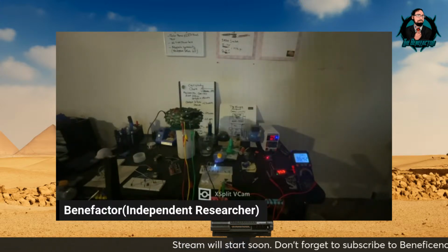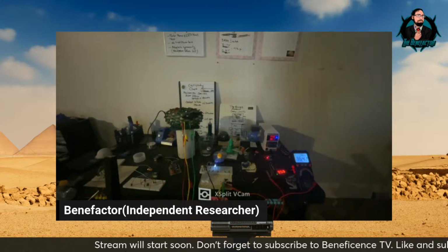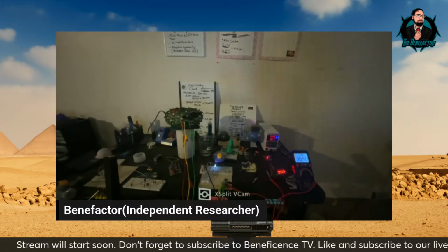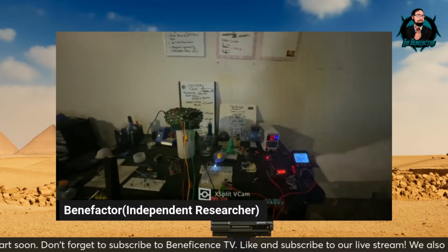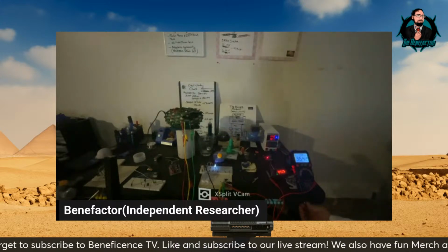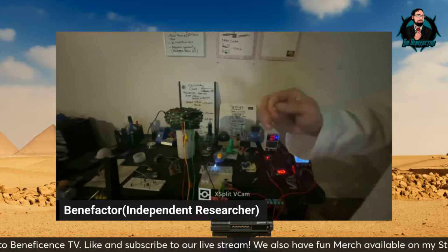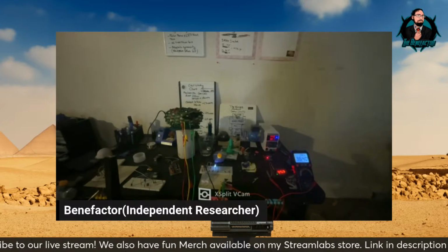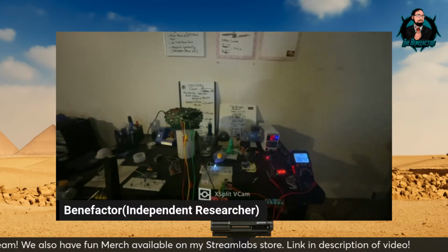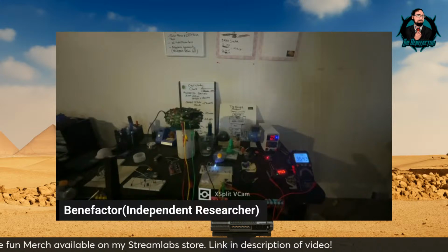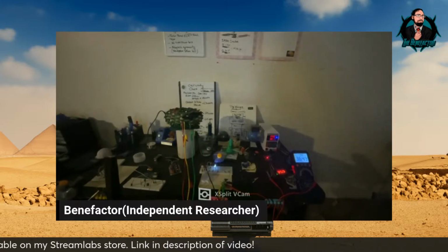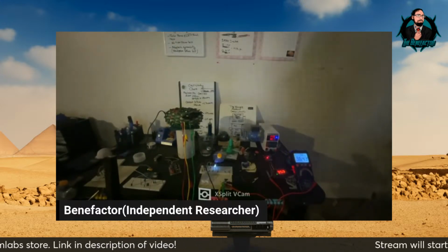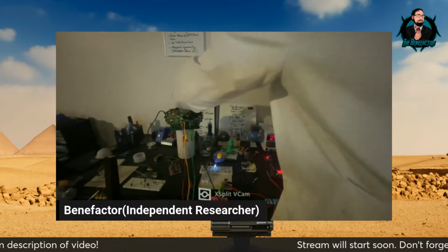Hey, Ben, you got that small magnet? The what? The small magnet? Yeah, the little tiny saucer one or the disc one. Yeah, throw it in there in the cup. And then turn your duty cycle down to about 30. Uh-huh. And then you're going to play with your volts and your amps a little bit, and try to see if you can get it to flow.